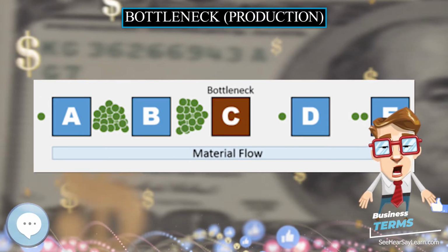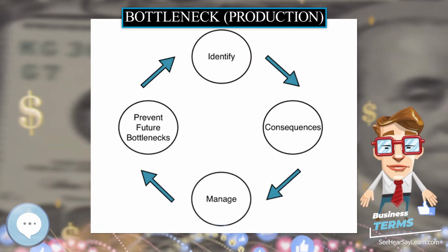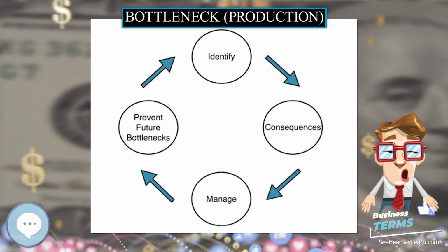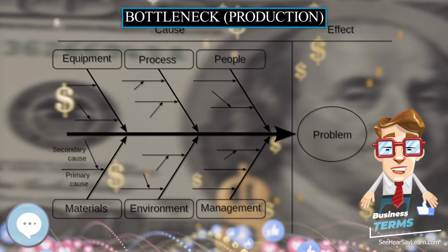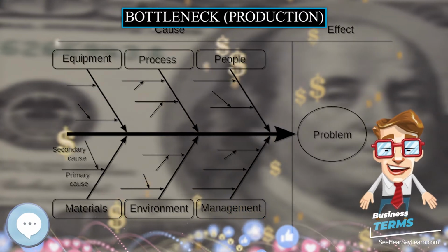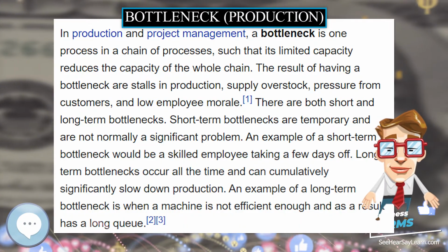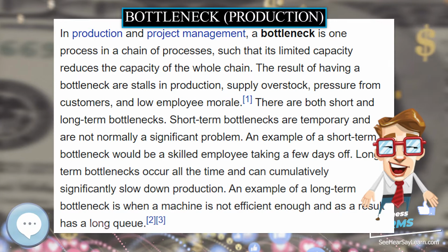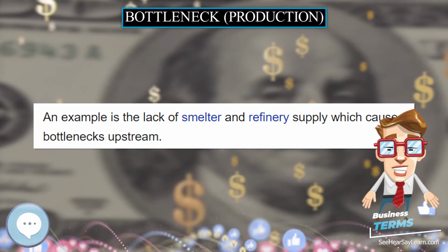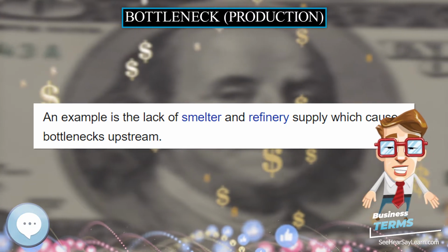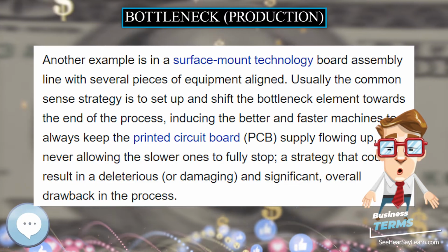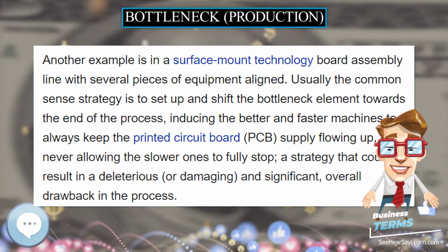Accumulation. When input comes in faster than the speed of the process, accumulation starts to occur. This means that the machine either does not have enough capacity, is not being fully utilized, is inefficient in use, or has an underqualified operator. This method is not effective at identifying bottlenecks where the queues are at several process steps, as there are multiple processes with accumulation.